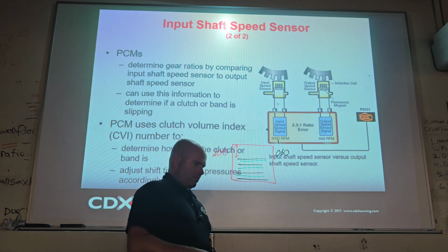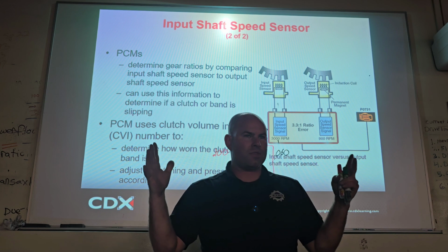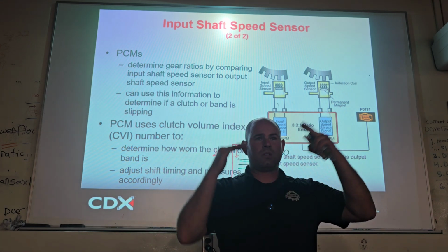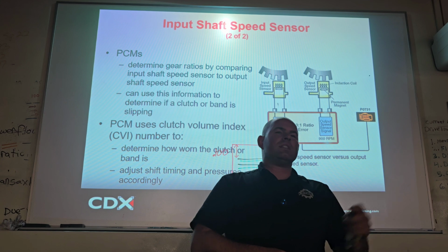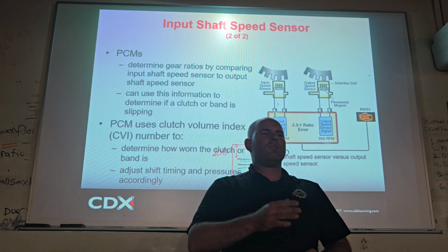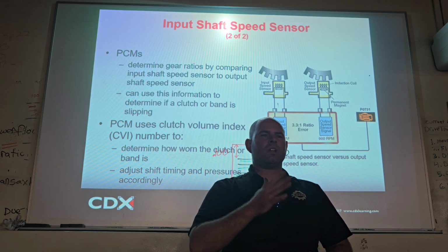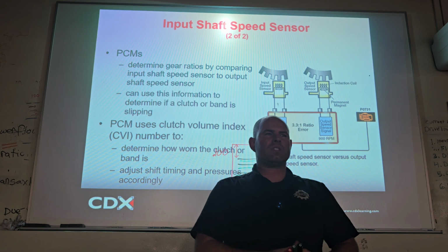Exactly. So from the manufacturer, you may have a range of 60 to 100 thousandths when you rebuild that transmission, and you'd measure it with a dial indicator. If one is set at 60 and one is set at 100, they're going to shift different. The customers don't want them to shift different. Every Chrysler 300 in that year should shift the same. How could we make them all shift the same?